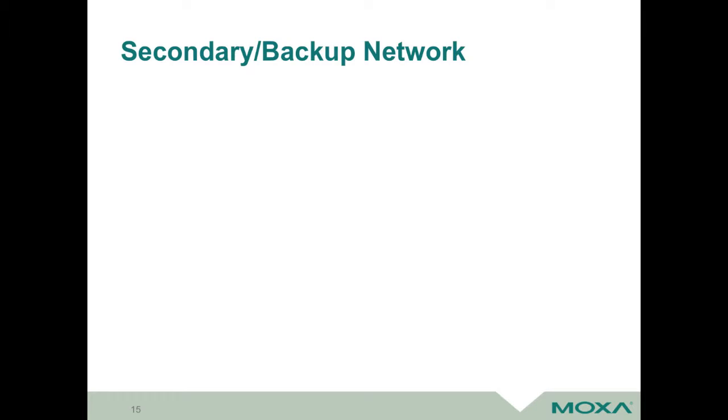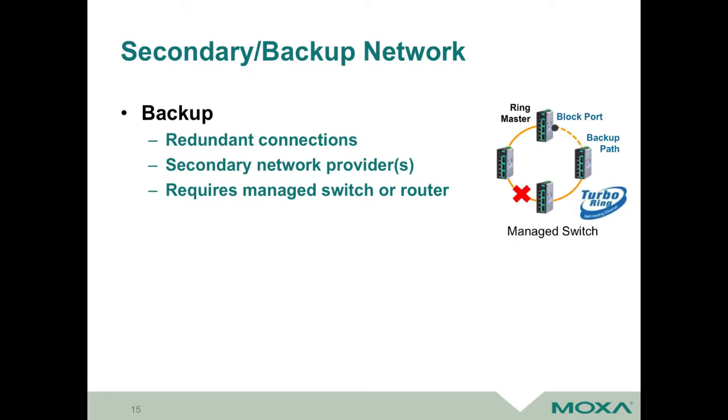So expect those disruptions. Let's talk about a couple categories of that, and in this I've got a bunch of little tips, and I think there'll be something for everybody here. The first one might be in a smaller remote monitoring system. If you can have a backup media connection, this is a great thing to do. So we're talking about maybe having Ethernet out to some equipment, or maybe a little beyond the scope of Ethernet. Remember, Ethernet goes about 300 feet max. It can be a little less, a little more. Your mileage may vary on that. You might do fiber on that.